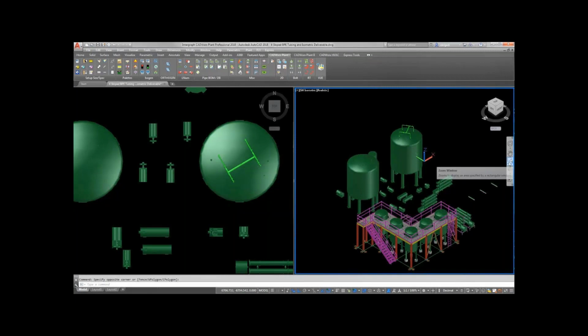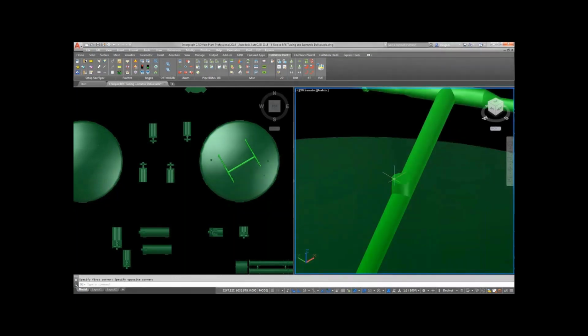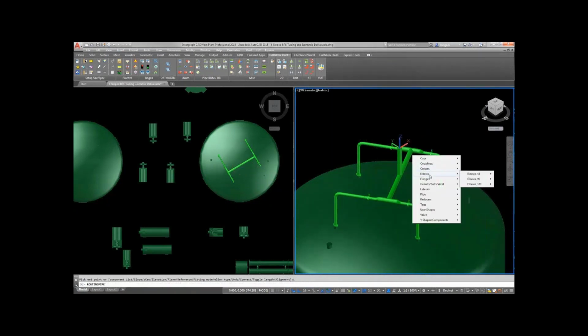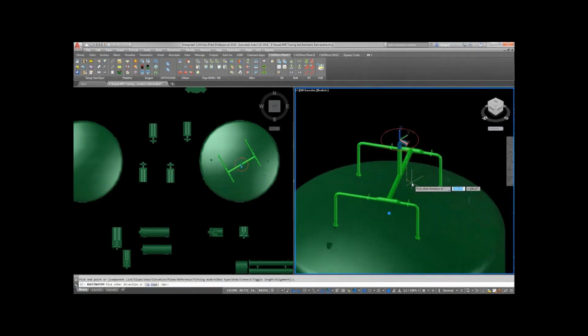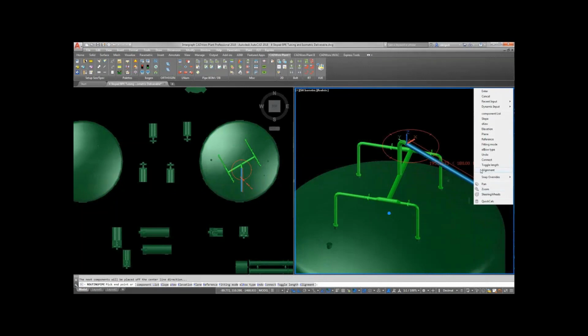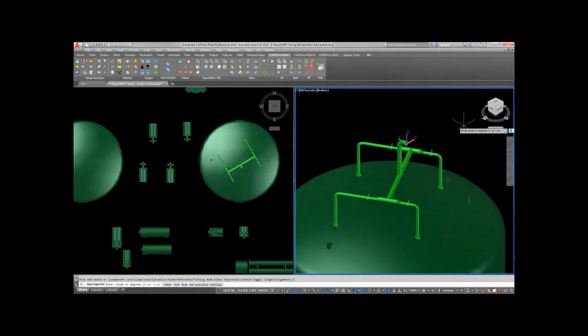Now, when going for the auto connection, in this particular example, I'm starting a routing from this T and defining a specific dimension for the height of this rise. Then I'm taking the skew for this, where I can choose the slope inside it. So I'm defining or choosing the respective options, which I need to do.